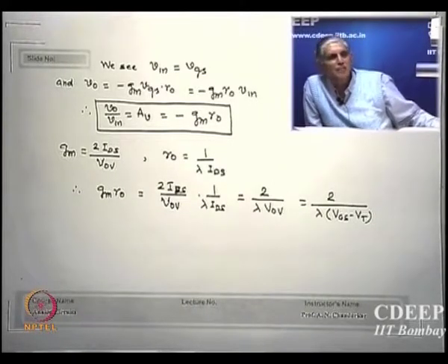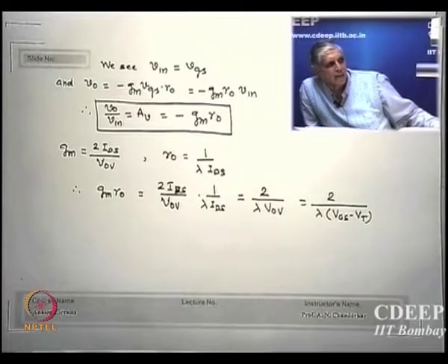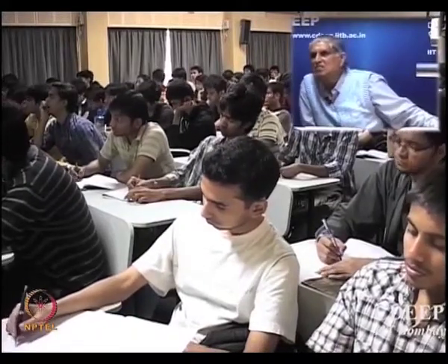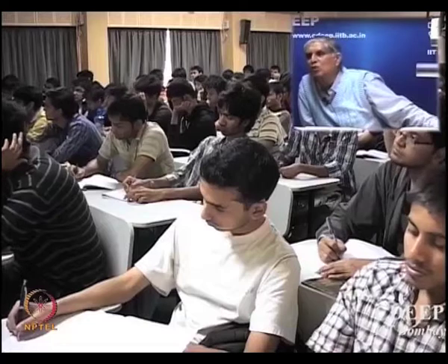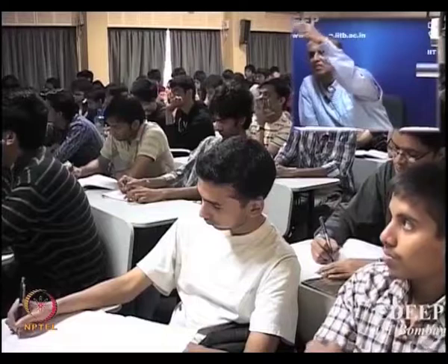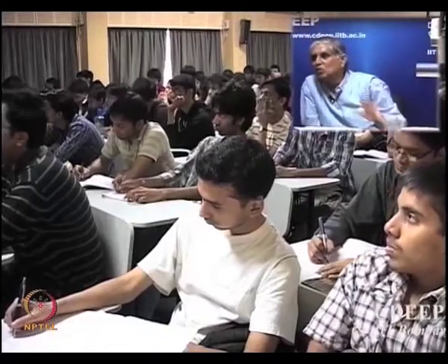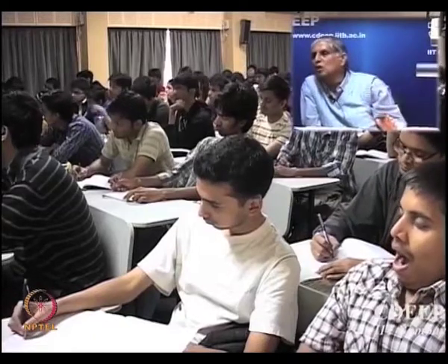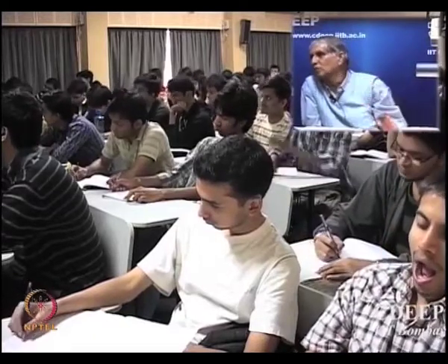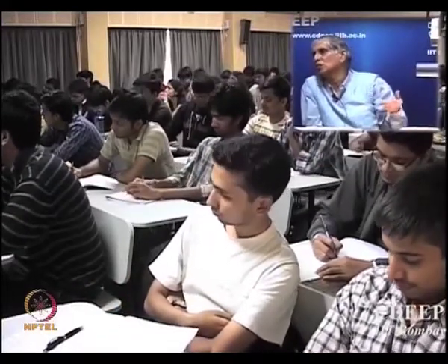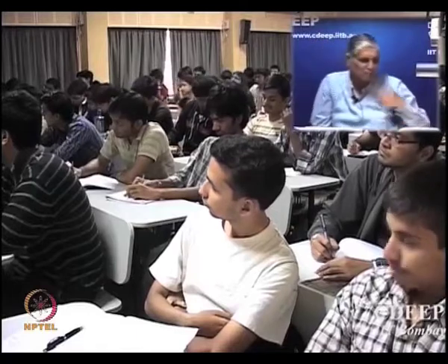So when I shunt it with RD, whether it will be more than 1000 or less, it will always be less than 1000, is that correct? So the typical gains you can get are 10 to 100 to 400, not even 1000, is that clear? 1000 is what we say is the upper limit. So an analog amplifier cannot intrinsically go beyond a few hundreds of amplification, but the actual amplification will be much smaller, as RD will decide. I will show why RD also decides something.